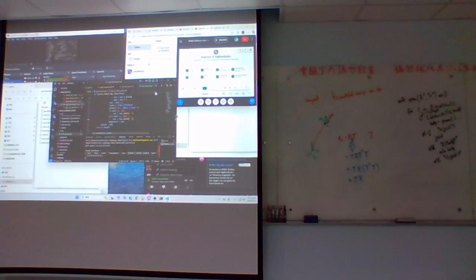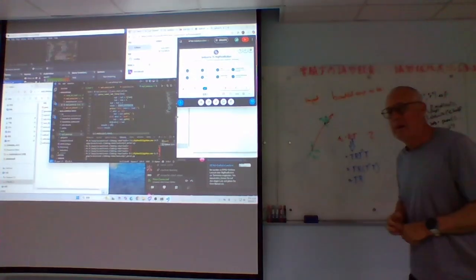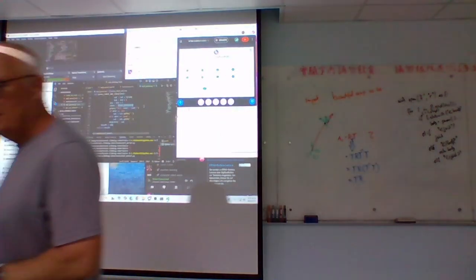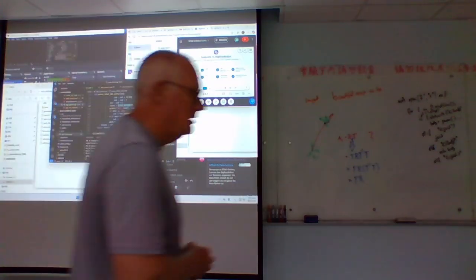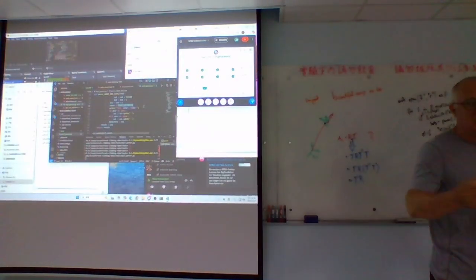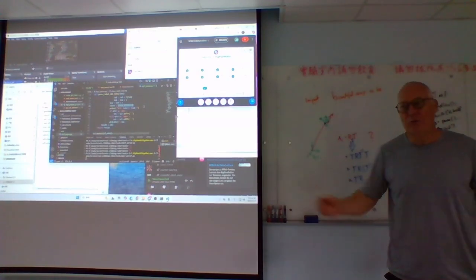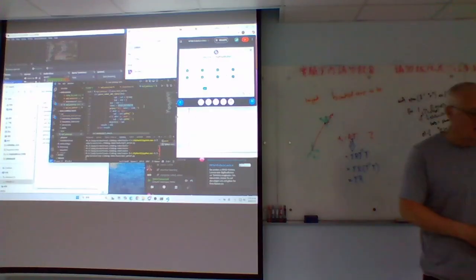And why, in the control menu in MuJoCo, can I not control my joint? You just have to give it the right values. So you need to set the amount of force that you have. Okay, no, you didn't define any controls yet. You just defined the joints. Oh, I don't have control, I just have the joint. I mean, you don't have any motors. You have joints, which are like hinges, but no motor. You need to tell it that there is a motor there.